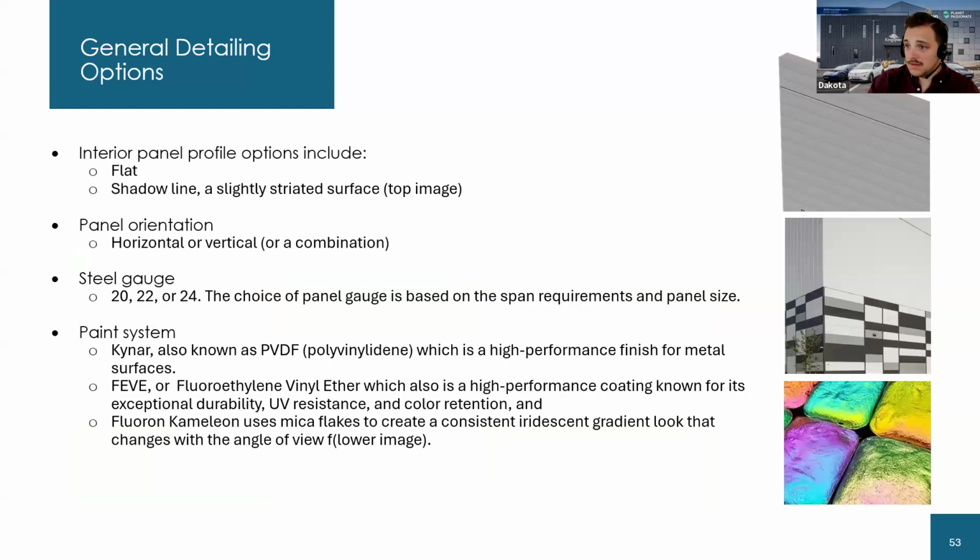Also, manufacturers can often distinguish between the interior and exterior finishes of a panel. Often the interior steel is going to be your exposed shadow line, often white because you're going to cover it with chipboard anyway. But if you're looking for something specific and you want to have it exposed, like we saw in that cold storage situation earlier on, you can do that. You can have it painted, you can have it colored, whatever you want.